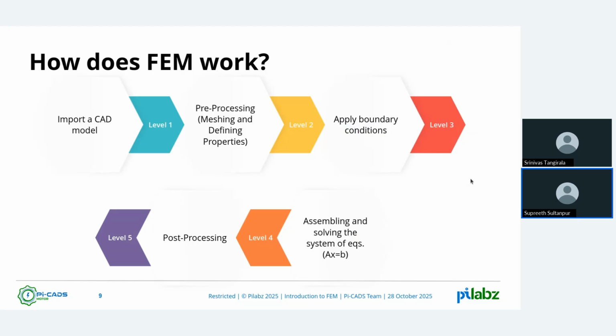So using these stresses and displacements, you can make a judgment whether you need any reinforcement for the chassis, or things like that, or whether you have over-designed it, you can remove some of the material, things like that.